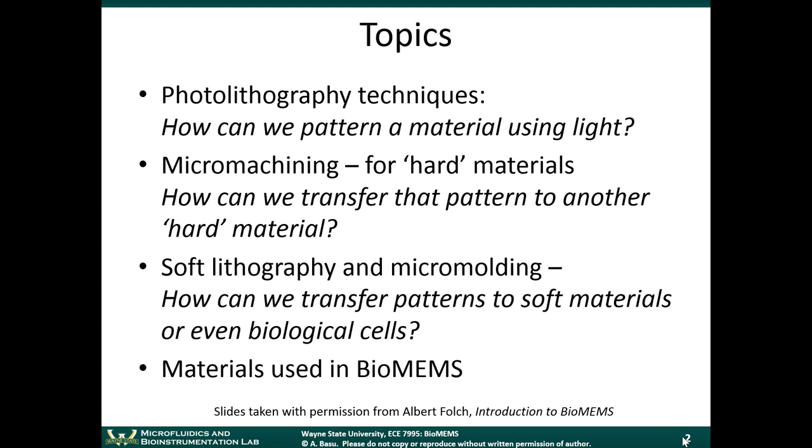Photolithography can be used to make devices quite small. Photolithography techniques have been borrowed from the semiconductor industry. So the same techniques that are used to make the microprocessors that go into your cell phones and computers have been adapted to make MEMS devices. MEMS, as you know, stands for microelectromechanical systems. The accelerometers that are in your phones as well are made using fabrication techniques that have been adapted from the semiconductor industry. And in fact, the MEMS and microfluidics fields have really grown out of the fabrication techniques from the semiconductor industry.